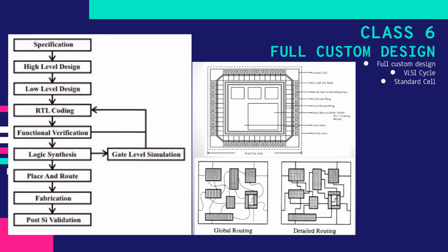Physical design, where you're converting your circuit description into a geometric description, which is then going to be used for fabrication of the chip, involves three steps, that is partitioning, floor planning, and placement and routing. So floor planning includes a sort of blueprint where you need to find efficient ways so as to have less delay, and routing is where you essentially make connections.